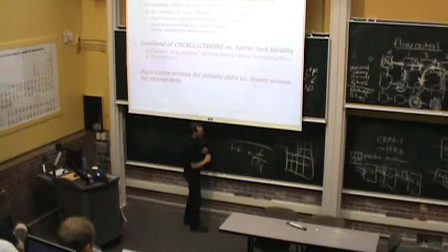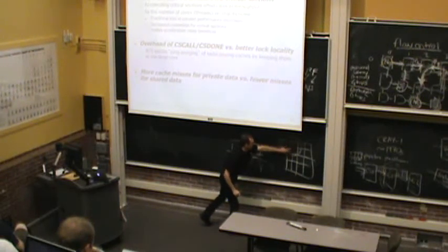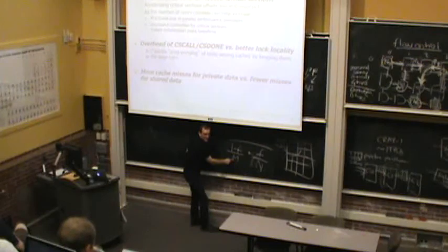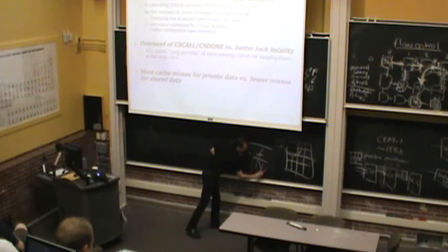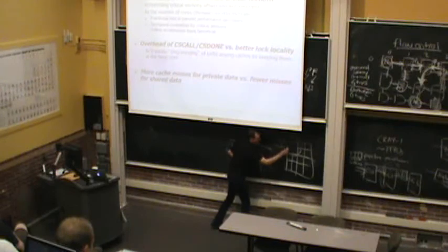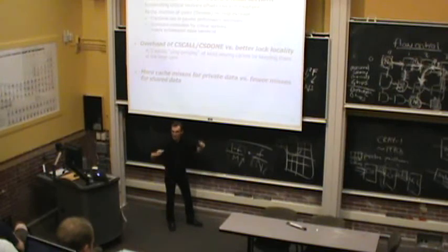But now what we've done is, if you will, added something else here, right? We're actually speeding up 1 minus f by m, if you will, compared to a small core. If you have a large core, it's m times faster than a small core. So we're now speeding up this portion also. Okay, so the trade-off is your n reduces because you're dedicating some of your chip area to a large core for an equal area comparison. But now your m increases as you dedicate more area to the large core.